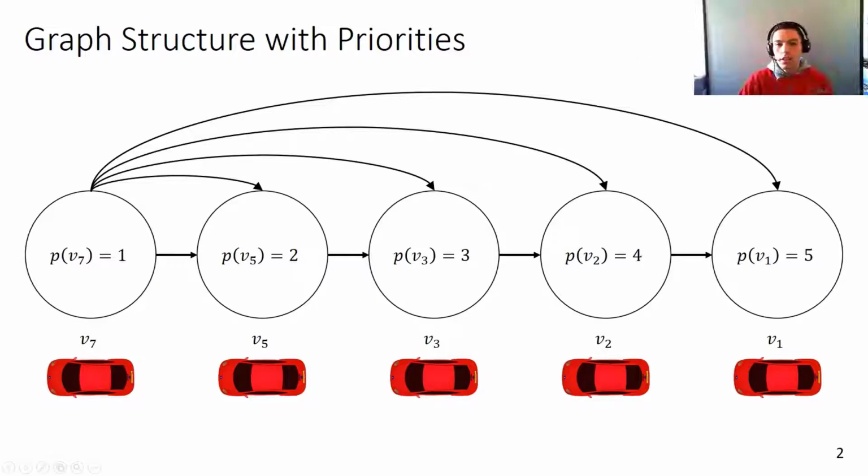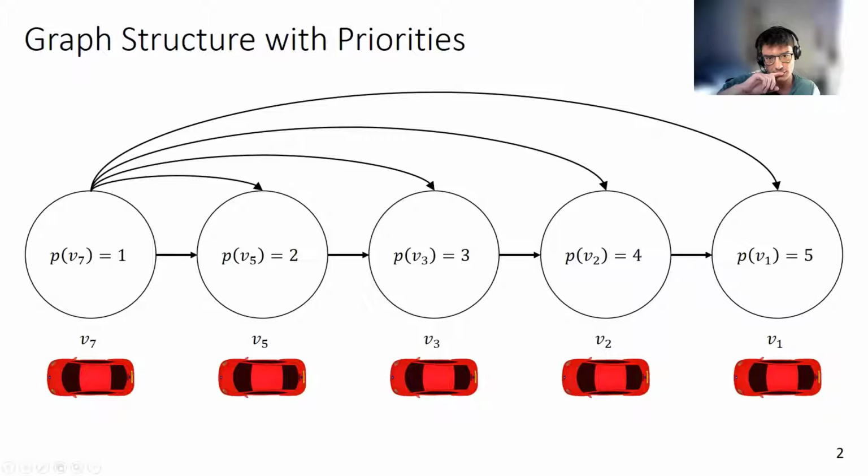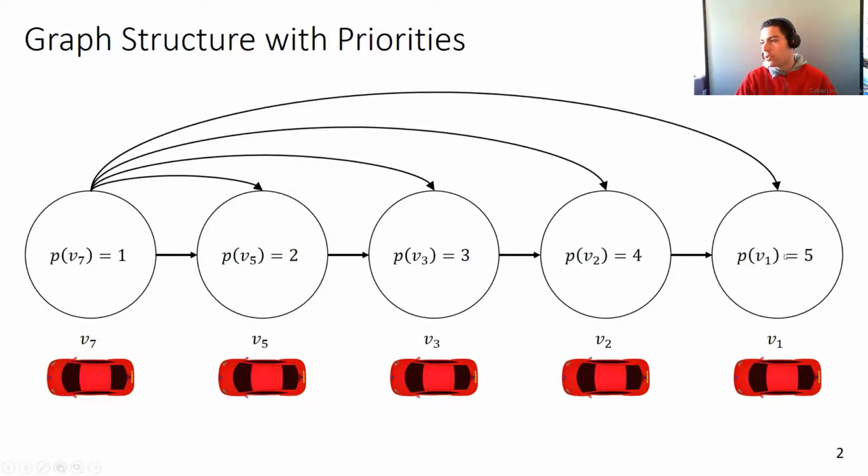You mean, that's a question to me, right? Yeah, yes. So vehicle 5 has lowest priority, so it should always wait until vehicle 4 has calculated, and vehicle 1 should always wait until vehicle 2 has calculated its prediction horizon.